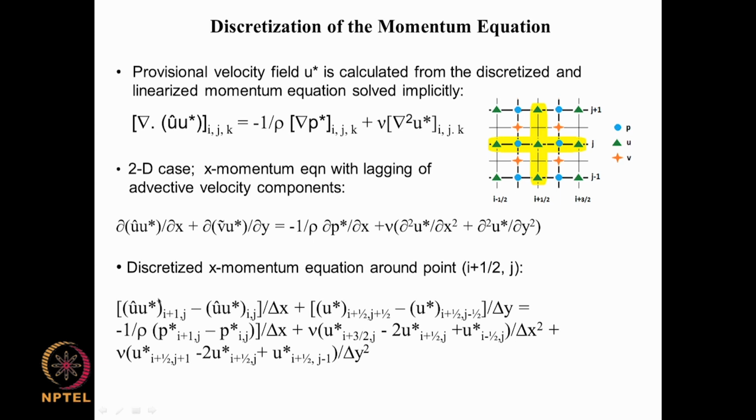So, when we make use of the upwind value, we are trying to fix the value of phi at this I plus 1, and we need to fix the value of phi at I minus 1. So, to be consistent with upwind, we say that the value of phi at this location is equal to the upstream value if u is positive. So, since we have an estimate of u from the previous iteration, we see whether that is positive.